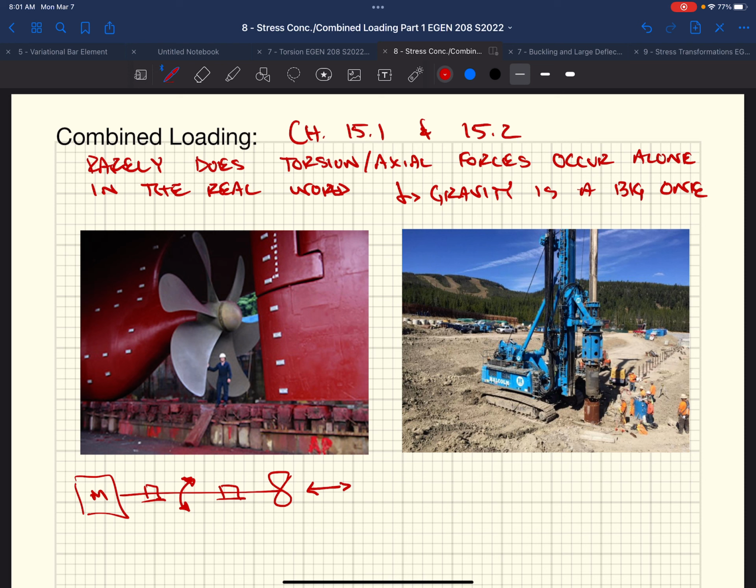And then on top of that, once we've figured that out, we're going to jump into stress transformations. If we have this combined loading, where when we were looking at the loading independently, maybe with axial load, the worst case normal stress is just going to be that force over the area, cutting a plane perpendicular. If we were looking at the worst case shear force, we were going to cut it parallel to the applied force. Well, when you start adding additional load sources, now we're going to have an axial load and a torsional load, and what ends up happening is it's some rotation of our material. You're going to find that we're going to have higher stresses than where we're actually calculating them at. Okay, so that's where we're headed.